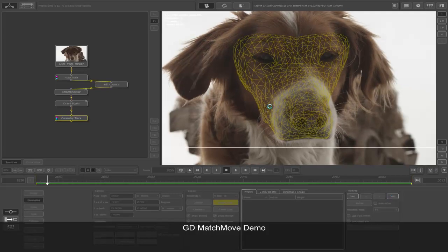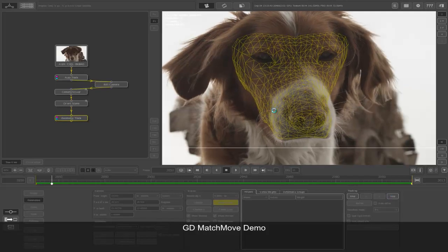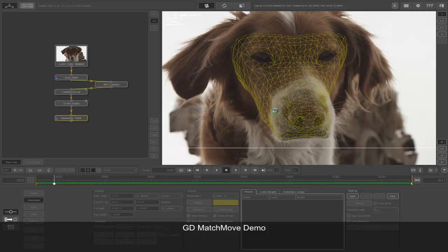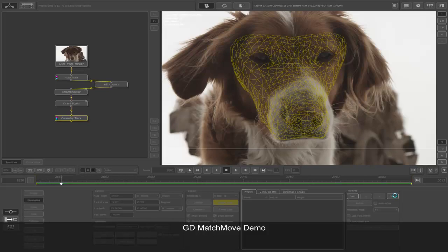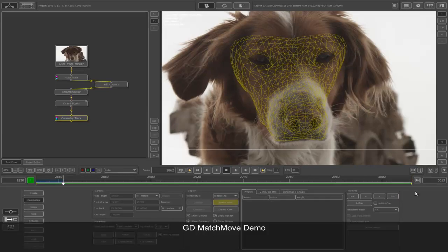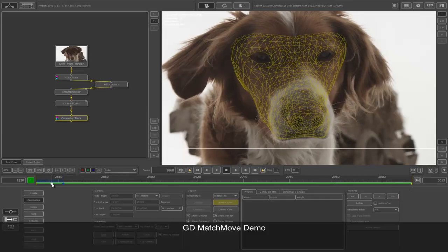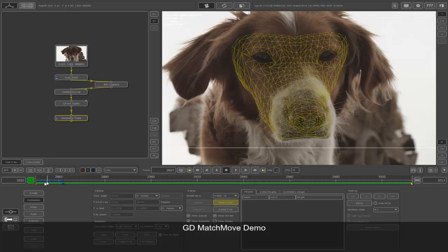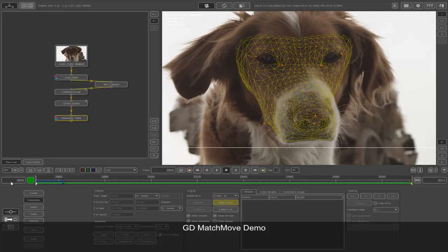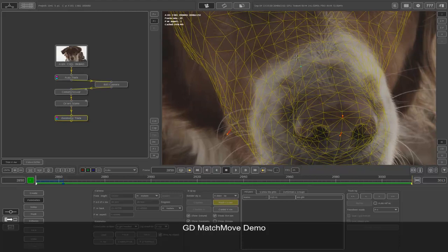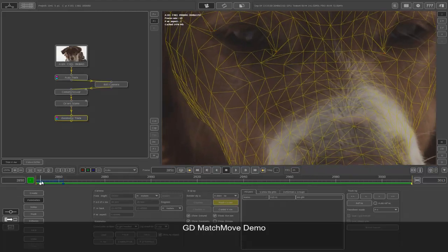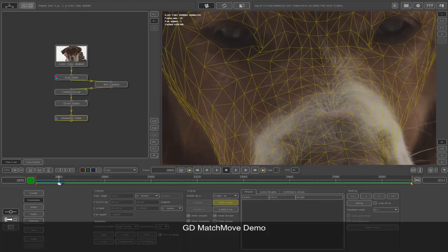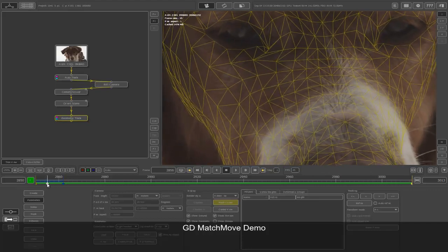The only thing to look for when you're tracking is to make sure the key positions, whatever you can see specific, stay the same. Okay, I'm at 2861, I'll hit stop, so that'll stop my track. And here I see my track is good, but it's not really exact. So why exactly am I saying that? If I zoom in, you can see the wireframe here. If I move across, you can see that it slips. It's not holding on to the actual object as such.